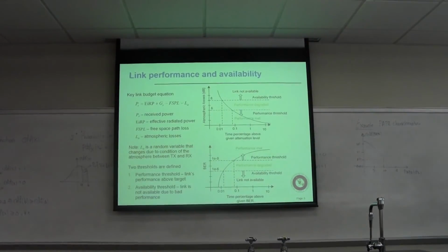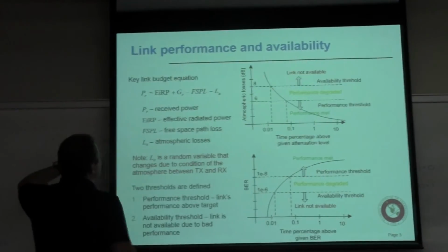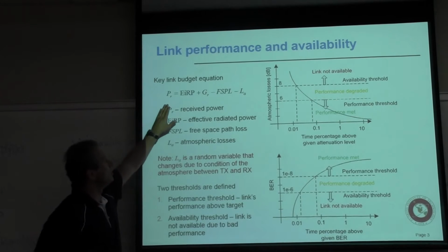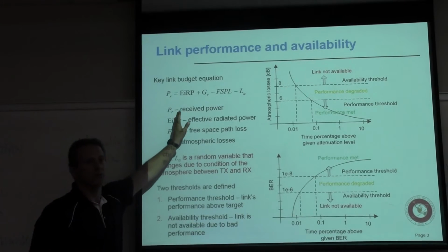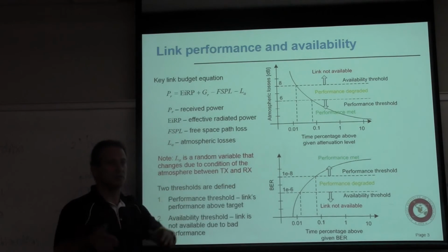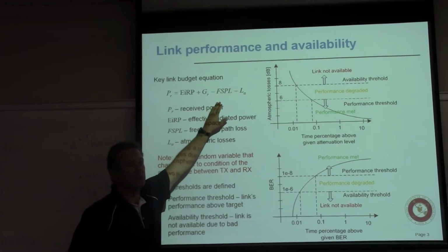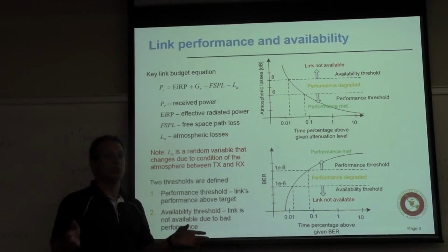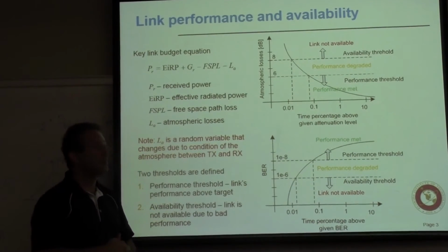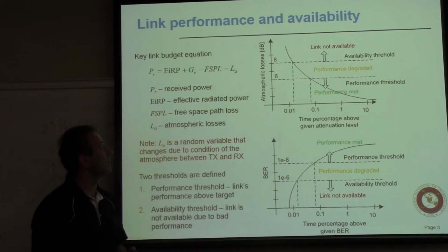So here's how we see our satellite link. We saw that ultimately, there are a lot of components of the link budget, but ultimately this is what it boils down to. You have your EIRP on the transmit side. You have your receive antenna with, let's say, losses that are associated with mispointing and all that stuff. Then you have your free space path loss, which is a big guy on the block. You have to count that one. You take that into account. But that one is easy because we have a formula for it and it's simple to explain.